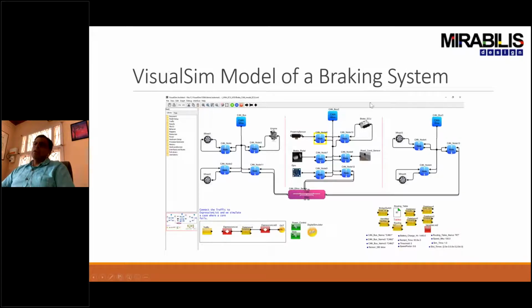That happens, the brake ECU starts processing that data and looks at all the others. For example, what's my angle, what's my engine RPM, it looks at other aspects like, for example, the road condition, and then determines how much pressure should I tell the wheels to apply, and it sends that across the network to all the different wheels. So this is, in a sense, the entire braking system of the vehicle. Now remember, it's only a part of the entire automotive EE. As we saw, this would become part of a larger system.